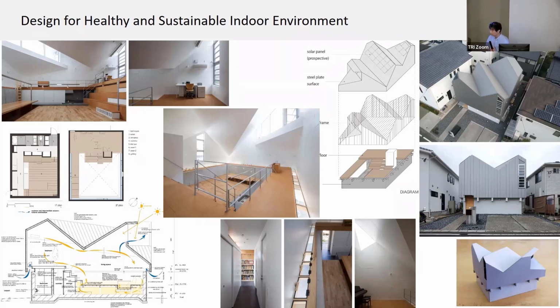This means during the winter season, I use the floor heating system. And during the summer season, we use the upper part air conditioning system, and relatively low air temperature is supplied from the upper part. Because of the negative buoyancy effects, low temperature controlled air moves from upward to downward. And I would like to say here, in this design, I gave up controlling the whole room, the whole air volume, and just focused on the local domain in order to minimize the energy usage for air conditioning systems.